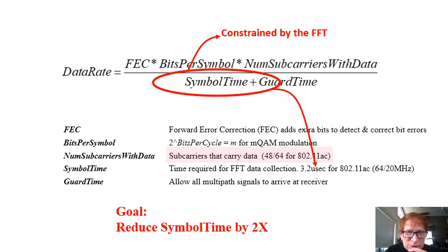Next, the subcarrier A and B is not fully populated with data. That is, 802.11, for example, has 64 subcarriers, but all of them do not actually carry data. Some subcarriers at the low and high ends of the bandwidth have 0 values for A and B in order to prevent interference or spillover into the neighboring 20 megahertz channels.